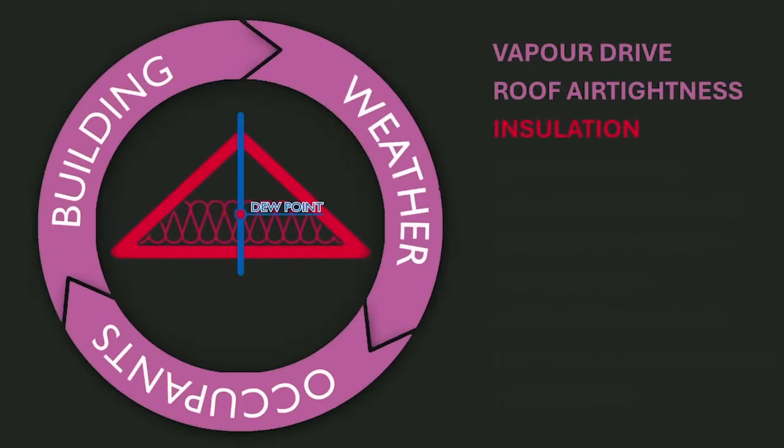If insulation levels are altered during the building's life, either as part of repair works or to improve the energy performance, then the effects on the balance of the roof system as a whole must be reconsidered. Wind washing describes the process of weather-driven airflow inducing additional heat transfer through the insulation layers. In extreme cases, this airflow can also affect the dew points by moving colder air further inwards.